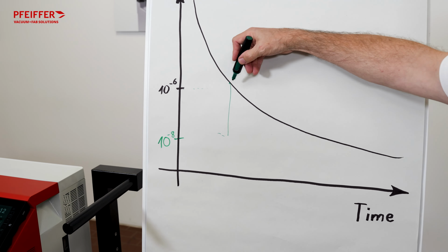Now, since we have a still declining signal due to the pump down, the zero function also updates, refreshes the signal every second. Imagine that we now have a signal of roughly 5 times 10 to the minus 8 millibar liter per second. This could be easily visible using the background function, and you can identify this much more easily compared to not using it.